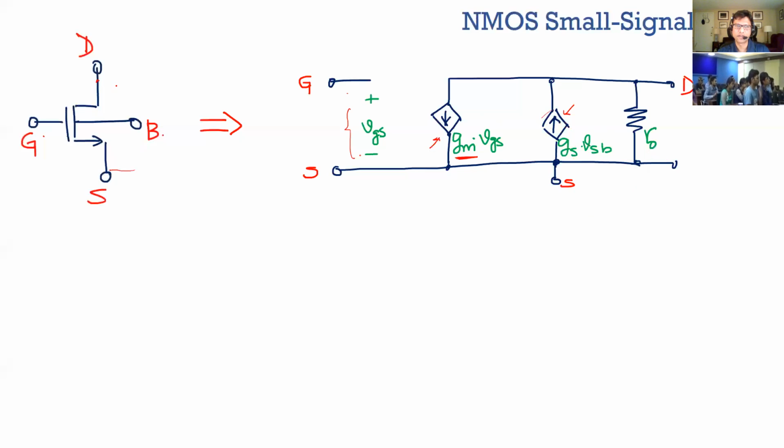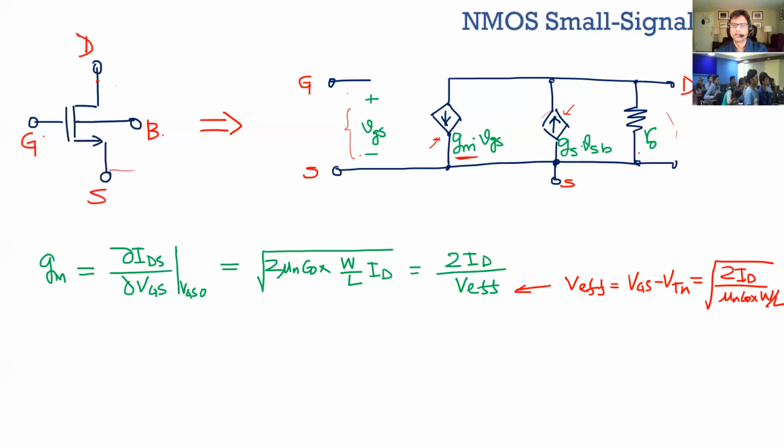As you change the drain to source voltage, the drain to source current changes very minutely, and that minute difference is modeled as your output impedance here. So that's really your low frequency small signal model. What low frequency means is that you're neglecting all the capacitors, right? The GM is really the slope, that is the IDS over VGS slope at a certain bias point VGS0. I've written VGS0, but it's true for VDS0 as well. So you basically freeze all the biasing, nothing changes.